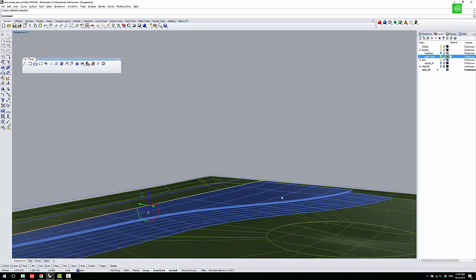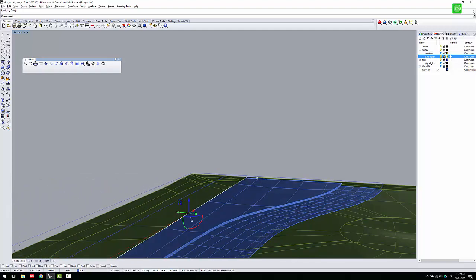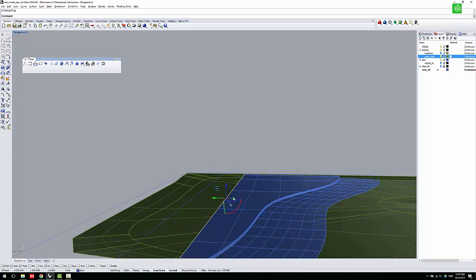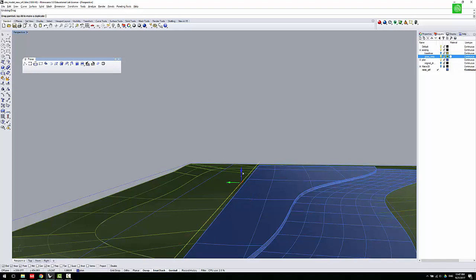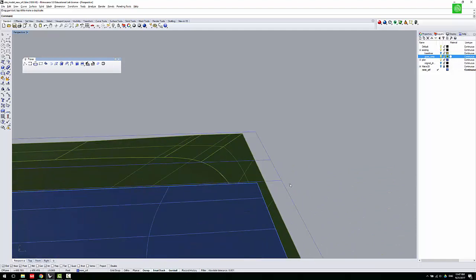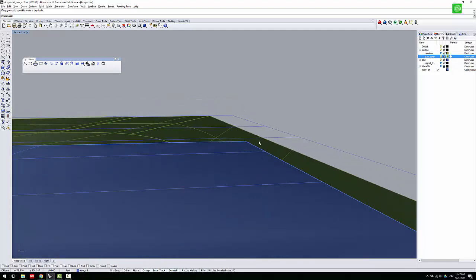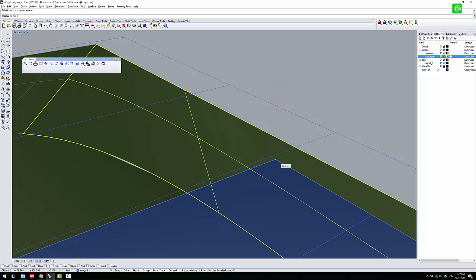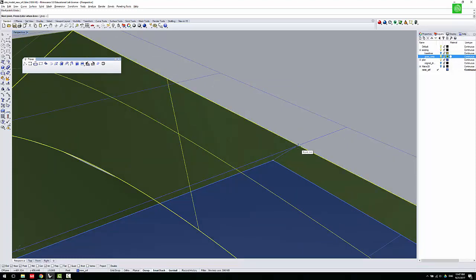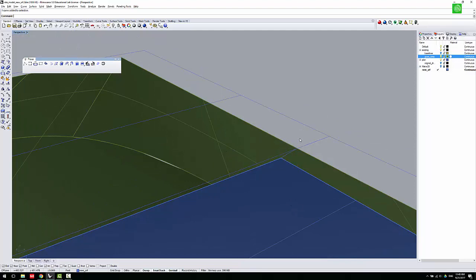Well, actually, this is not what we're going to do. Sorry about that. So what we're going to do is this line, because we want to move up 0.5. So we have this line. See here, it's perfectly correlated with each other. And then I use the interpolate from surface tool. I click the surface and hit the points. There you go. I have one line down here.